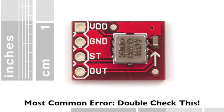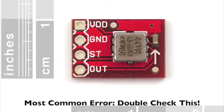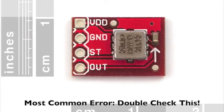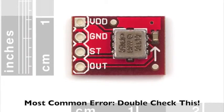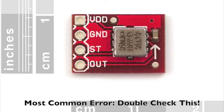If the accelerometer is recording but isn't registering any variation, you should check to make sure that the arrow on the breakout board is pointing in the direction of accelerometer motion. Since the accelerometer is a single axis, it will only measure acceleration in that direction.